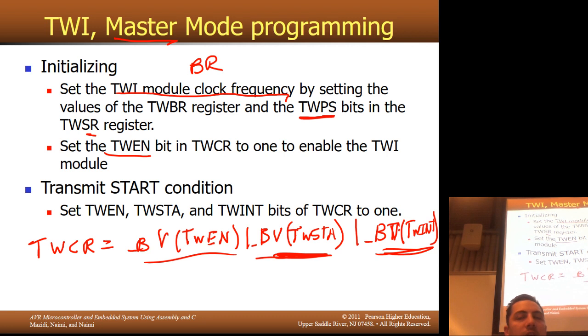If you were to immediately read the control register right after you did this, you would not see the interrupt bit high. It's one of those weird hardware mapped registers that has special purposes built in. So this is how you create a start condition. If we were building up an abstraction library, you might have something that says TW_start_condition, and this would be all that's in it. But it abstracts away all of the registers. So that's the start condition.